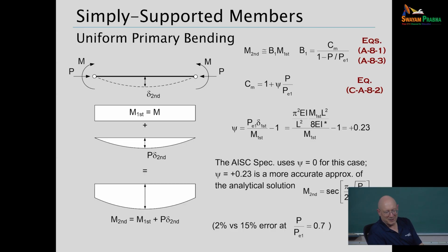Of course, this is where we can wave our hands a bit and kind of wave it off. In design practice, have any of you ever designed a member in uniform bending? Would the end conditions be pinned? Probably the closest to this case might be if you have a strut, maybe a WT section or something like that to gusset plates, and you're delivering the compression through the gusset plate.